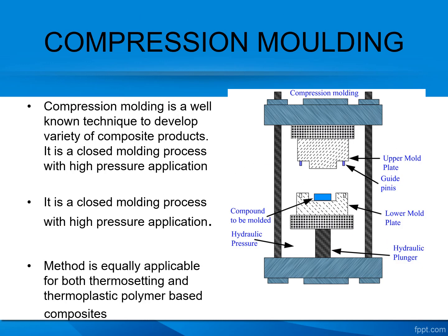Okay, so next method is the compression molding method. The compression molding method is widely used in automobile and aviation industries because we require high strength products. So we have to go for the compression molding process rather than the hand layup method. It is a very well known technique, so people already know about it.